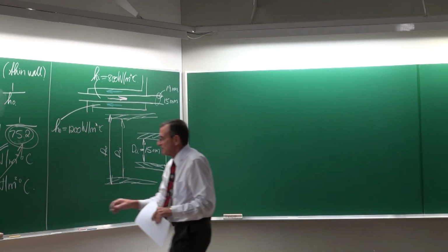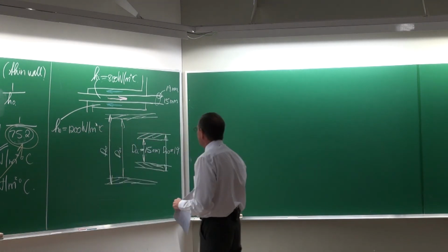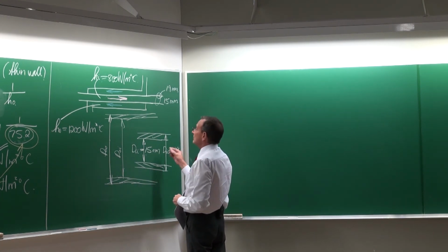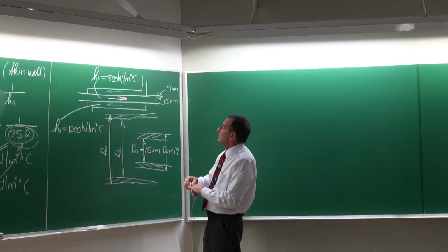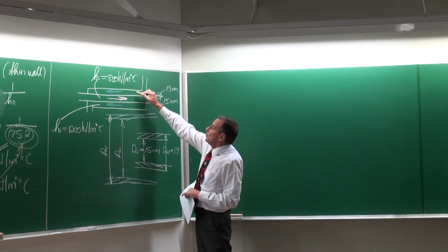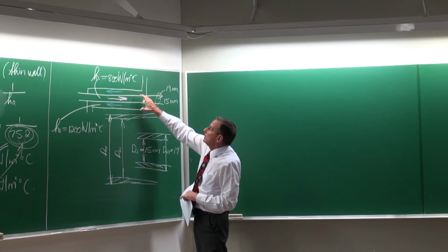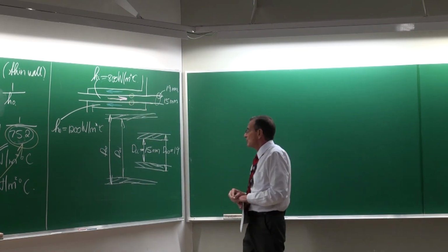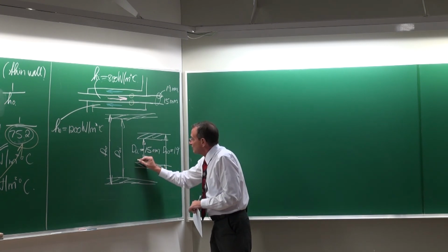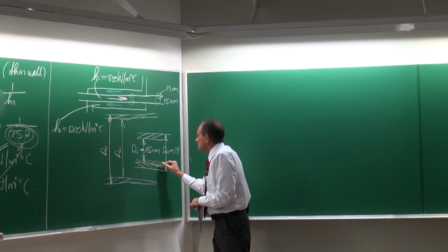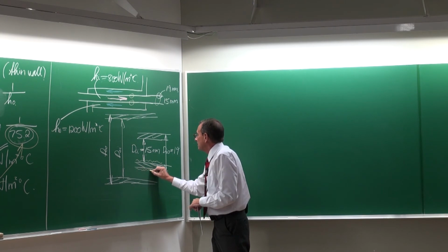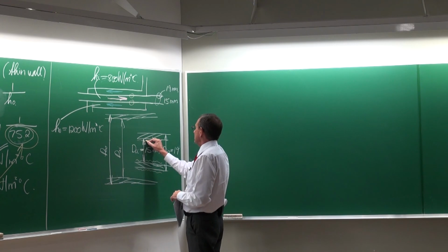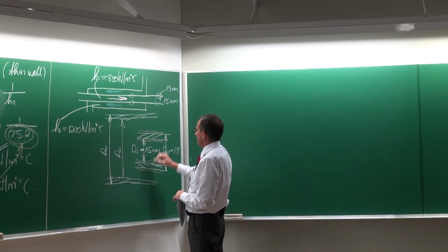And then they're going to give us some information on fouling. Remember, fouling is not normally going to happen in the annulus itself, it's going to happen on these surfaces there, where you've got the heat transfer. So it is that surface there, and there's going to be fouling there, and then again there and there.